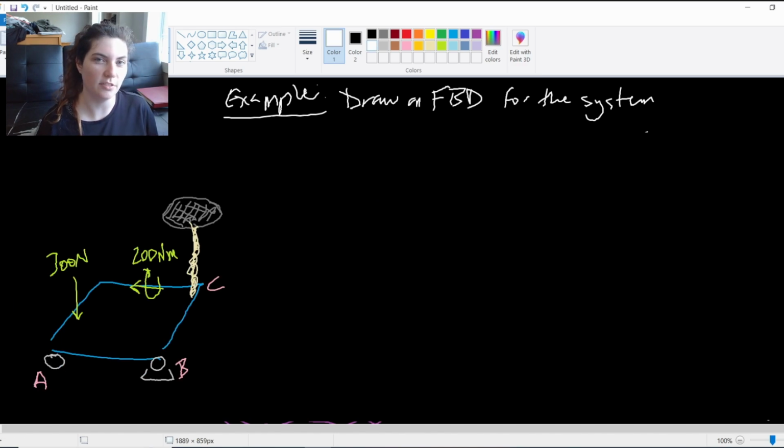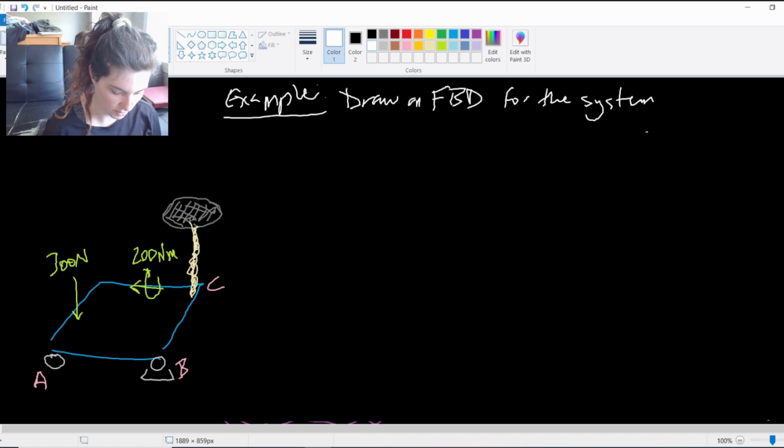Let's take a look at one final free body diagram here. Here I have this plate that is supported at points A, B, and C, and each of these supports are a little bit different. So at A, we have this little ball. This little ball allows movement in all directions except one. It acts directly up as like a normal force onto this plate.